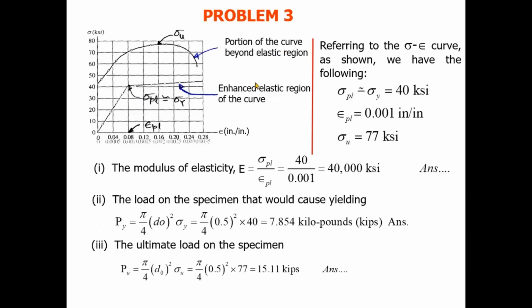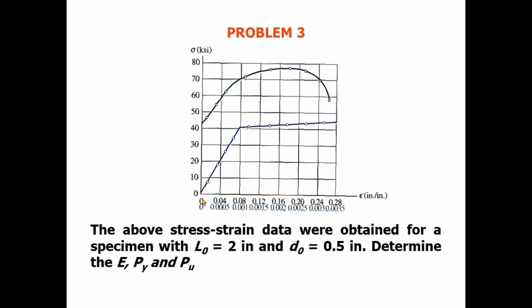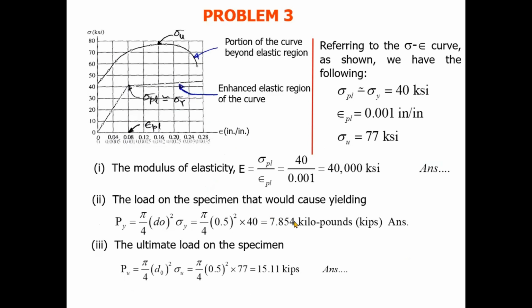Now, what is the modulus of elasticity? Stress over strain over the proportional limit. Okay, we can see here clearly this is the proportional limit. Then it changes into a curve. So we will drop the value here and here, and we can determine stress and strain, and then calculate the modulus of elasticity.